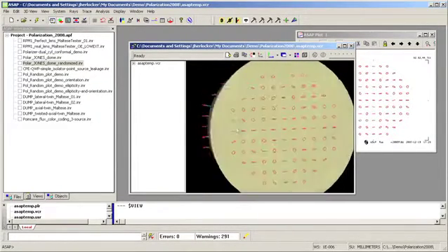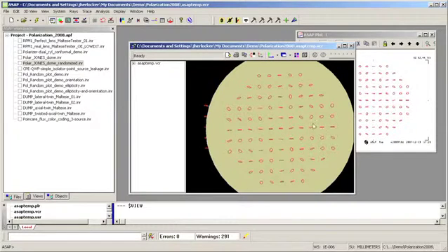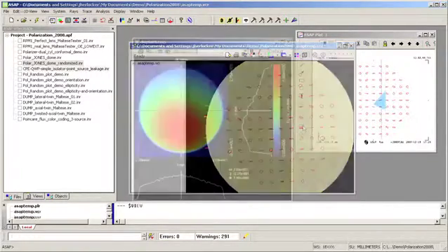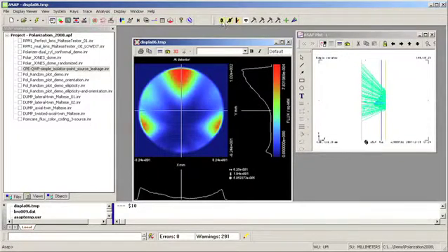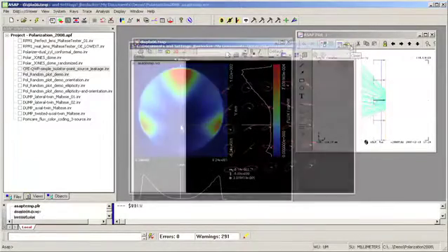Such a quarter-wave retarder can also be examined using rays with their polarization states randomly perturbed, a new source randomization feature. Simulations may include individual polarization devices that are cascaded. For instance, a one-way isolator model is a cascaded realistic polarizer and a Jones quarter-wave retarder. With off-axis illumination and a skewed device orientation, a skewed Maltese cross results.